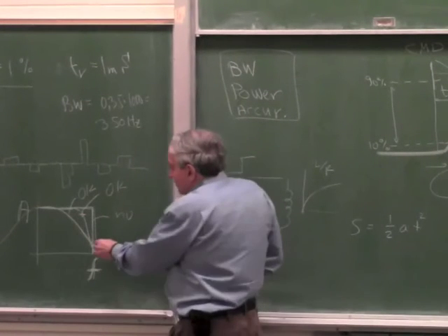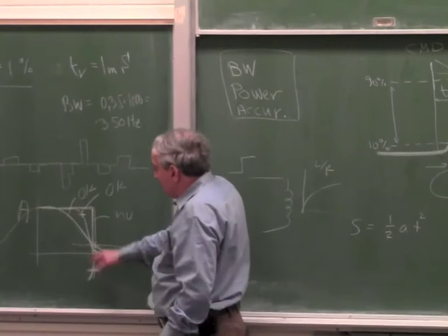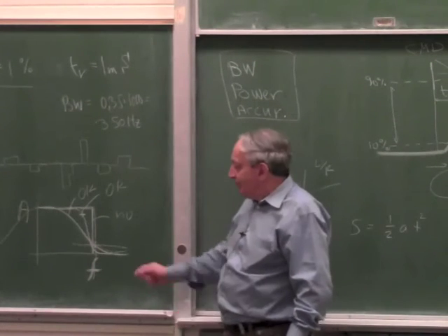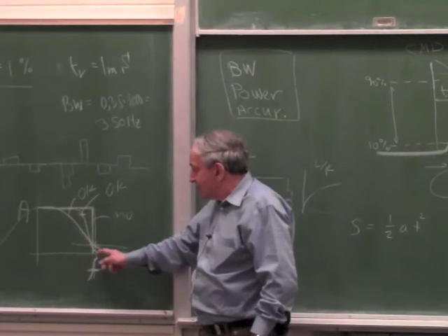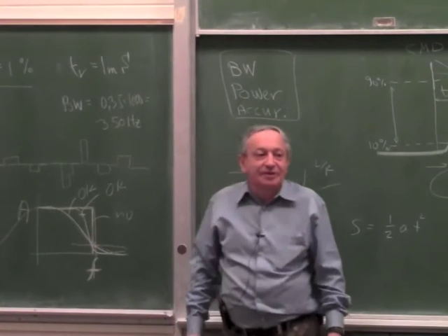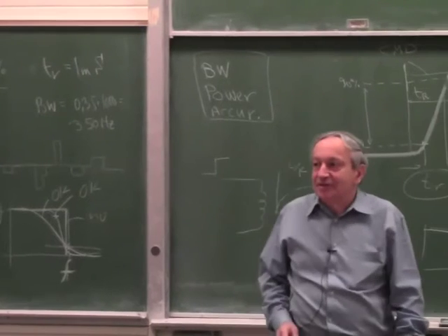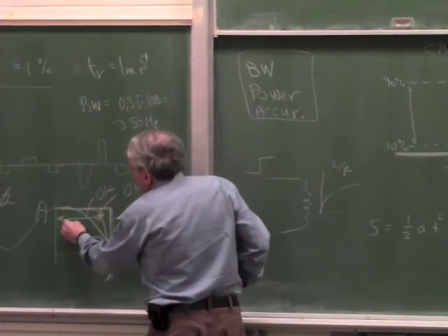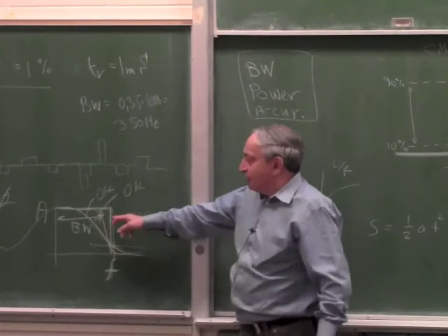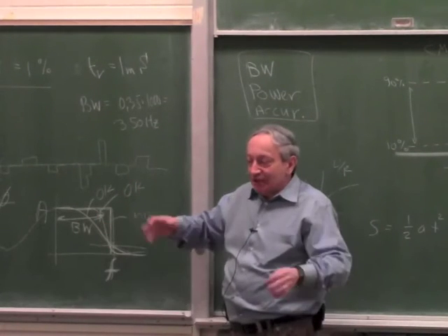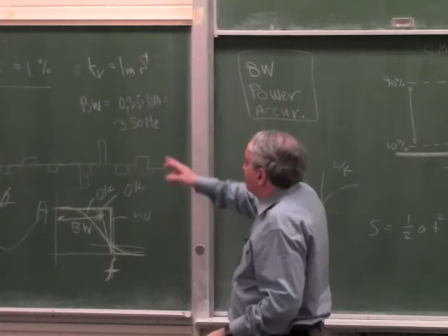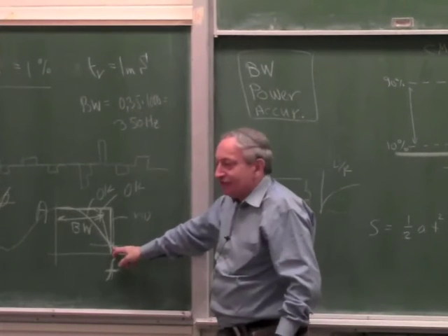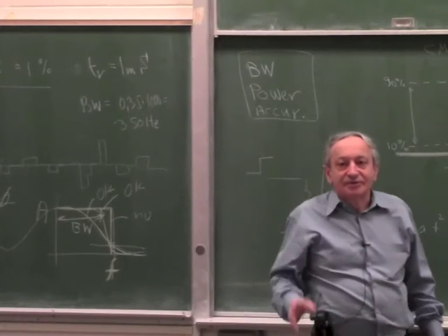The most important point is here. Let's say I want the filter to cut off at a certain frequency to a certain amount. Does somebody remember how I know at what frequency the filter should cut and to what amount, in order to specify the filter? Because the bandwidth of the filter is measured here. This is the bandwidth of the filter. It's usually measured to the 3 dB point. So I can easily calculate the bandwidth of the filter. It has to come out a bit more than this. But how do I calculate the cutoff of the filter at the bottom? Can somebody remind us?